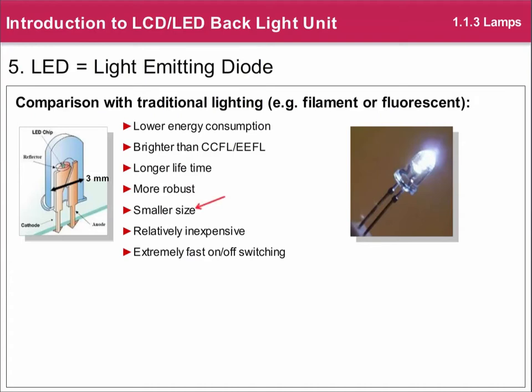The LED chip is very small, mostly less than 1 millimeter square, and is actually a diode that conducts the current only in one direction. The light output is dependent on this current. We control the current carefully by a special electronic circuit because there is not a filament that wears out and can break. The LED is very robust. It has extremely long lifetime as well.